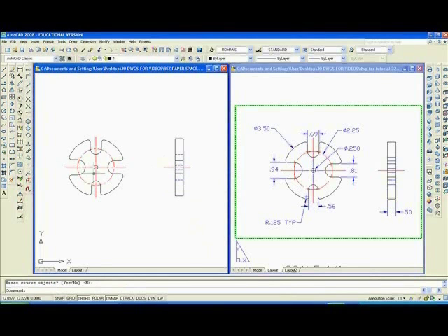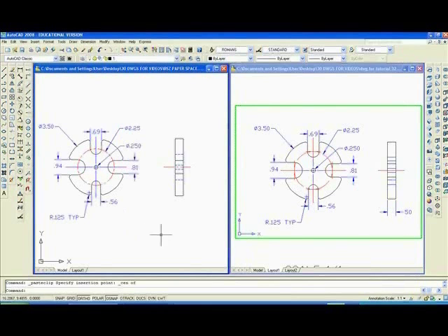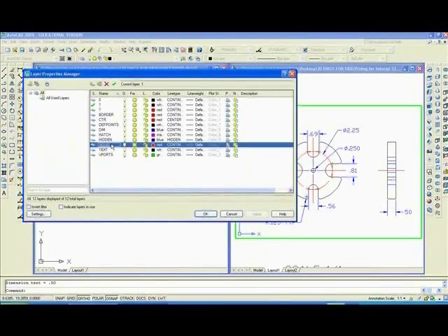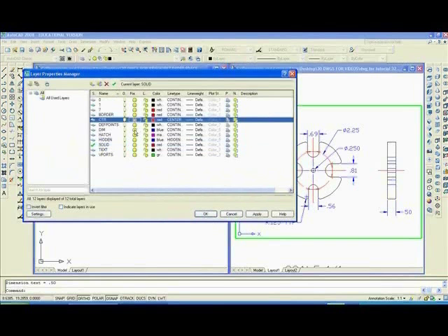But rather than take your time in dimensioning it, I'll just dimension it without using the video. Then we'll move on to making the solid. And I'll put the final dimension on now. And we'll want to proceed to make a solid of this object. So I'll click on Layer and make the solid layer current. Probably freeze the center layer, freeze the dimension layer.